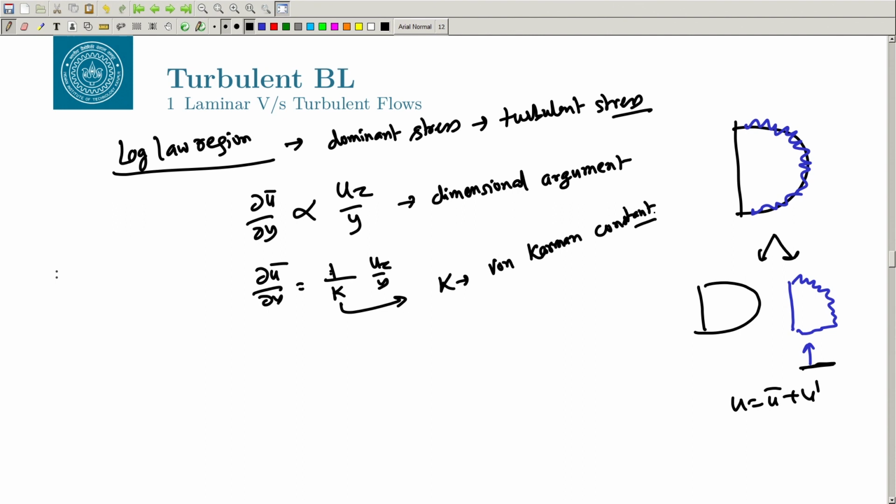In fact, before Prandtl there was not much understanding of the boundary layer. People believed that if the flow becomes highly turbulent, the boundary layer is very thin. As you keep increasing the Reynolds number, the region where viscosity has an effect gets closer to the wall and becomes thinner and thinner. So, people thought you could ignore the effects of viscosity if the flow becomes very turbulent.